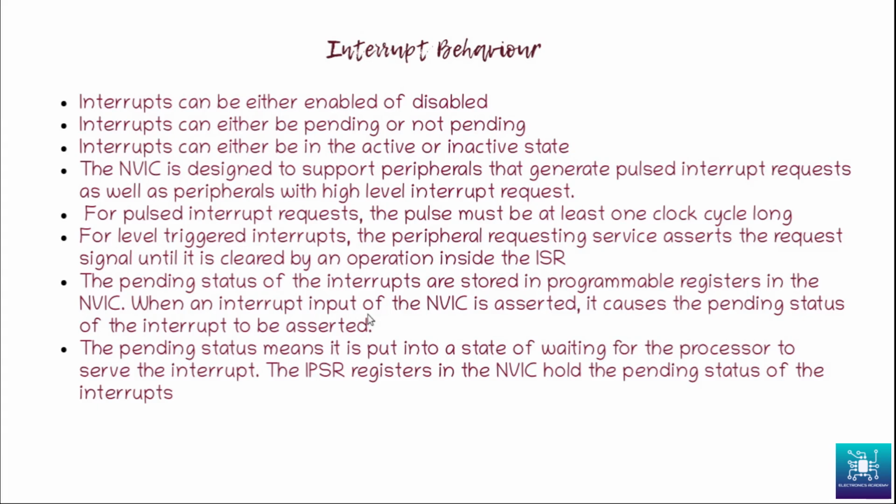So let us further discuss the interrupt behavior in Cortex M4 in addition to interrupt grouping. As we had discussed previously, we had seen the registers also. Interrupts can be enabled or disabled. Interrupts can be in a pending state or it may not be pending. Interrupt can be active or inactive, and the nested vector interrupt controller is designed to support peripherals that generate pulse interrupt requests as well as peripherals with high level interrupt requests.